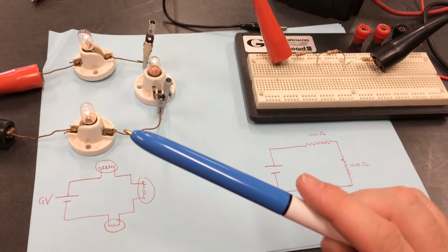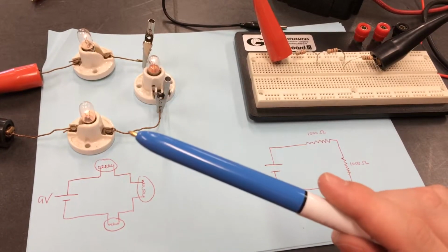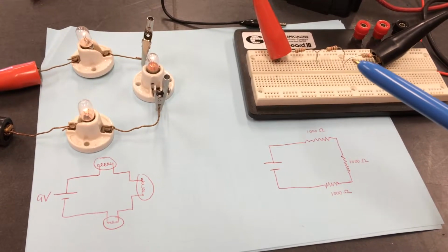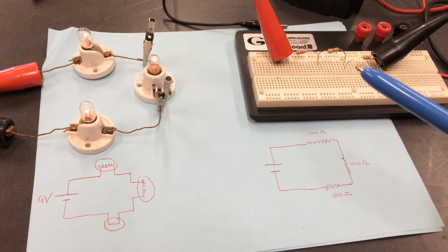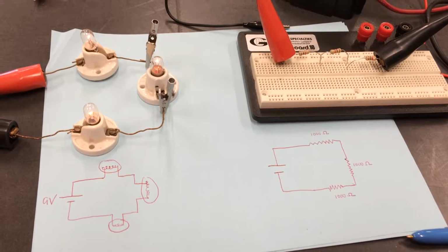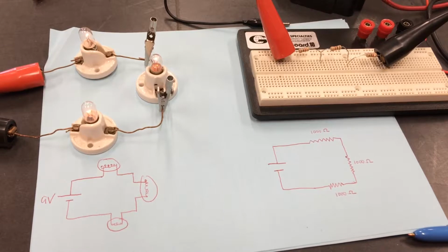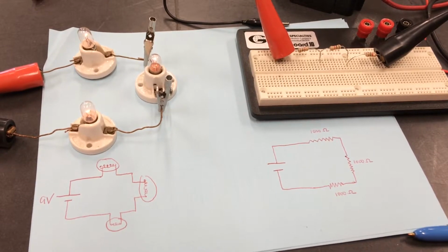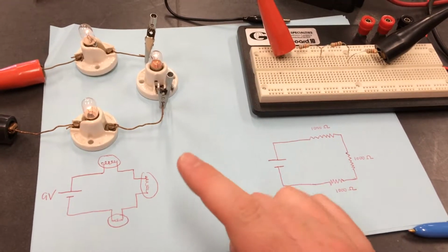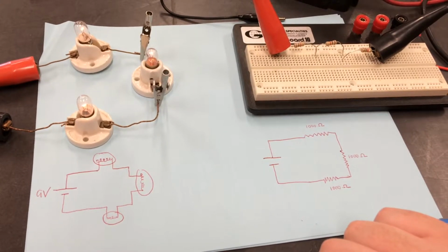But the light bulb converts it into heat and makes the wire inside very, very hot, thousands of degrees, which is why it's glowing like that. This doesn't make it that hot. And that makes this a better choice for studying the basic laws of physics than the light bulb. Because charge and its ability to pass through a conductor changes based on chemistry of an object changing, based on how the atoms behave. In a light bulb, the atoms behave pretty complexly because there's huge temperature changes here. There's not in a resistor, and that makes it a little bit easier to study.